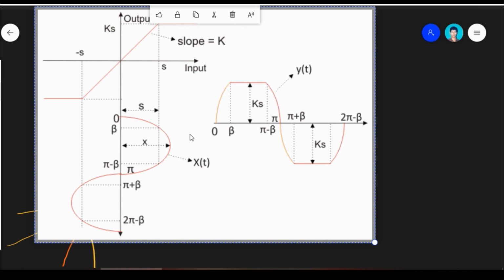If we consider the inductor as a system with current as its input and flux as its output, then after our current exceeds its saturating limit, we will not see any tangible change in our flux level. So that is a very interesting thing to note, that for a linear system you can only draw a phasor diagram.